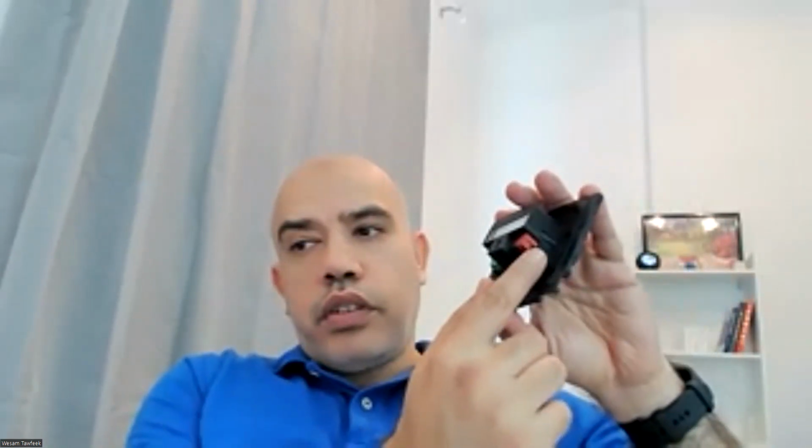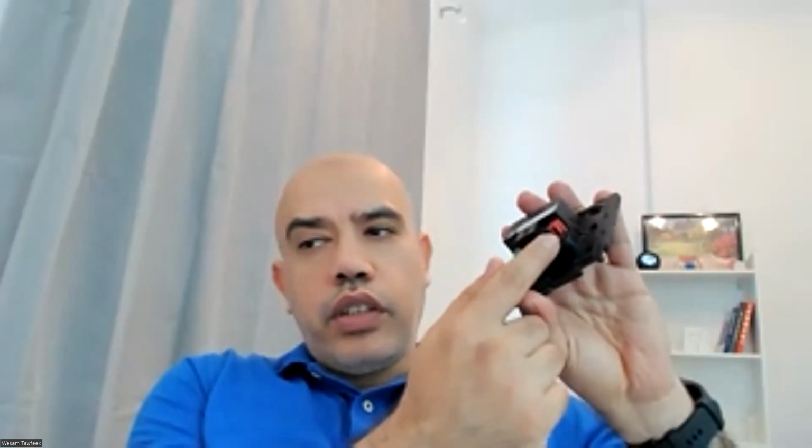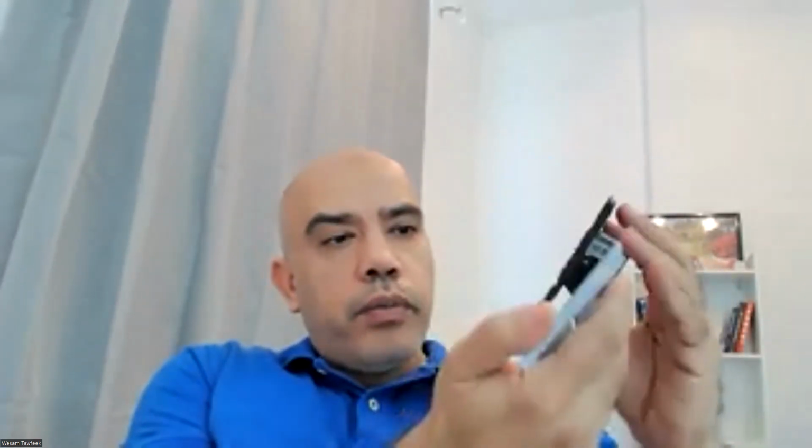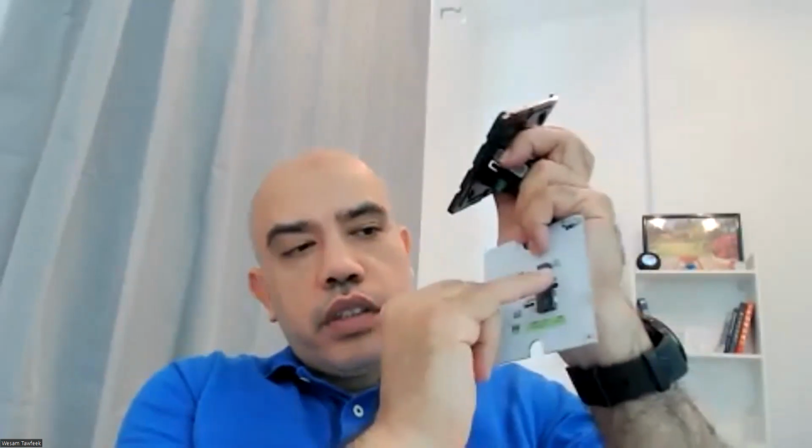This is the one connected to the KNX side, using this interface. We'll talk about this in the installation, but you put the cabling in here, in the wall, and then you attach the application module to it by this socket. You see this socket?